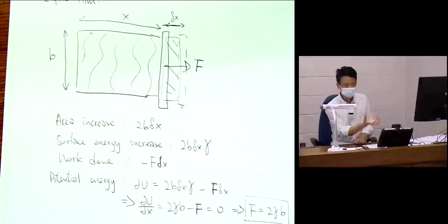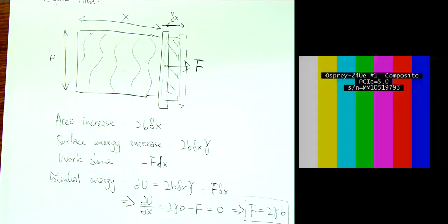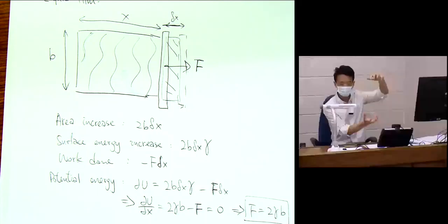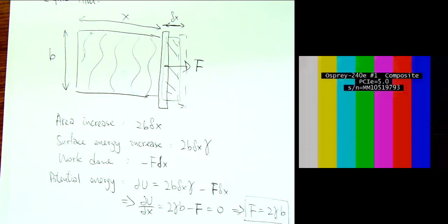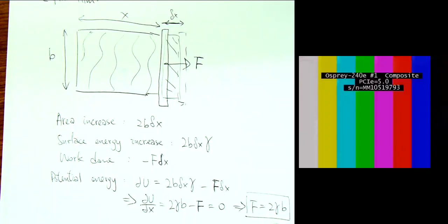You maintain the force constant by putting a constant weight there, right? So there's the gravity force, just holding it, and once it stops moving, that's an equilibrium. Everything stops. Surface energy is balanced completely by the weight force of the load you put on. At that point, you mark down that is the force, and that is the surface energy of the glass. Okay, so that's the glass.